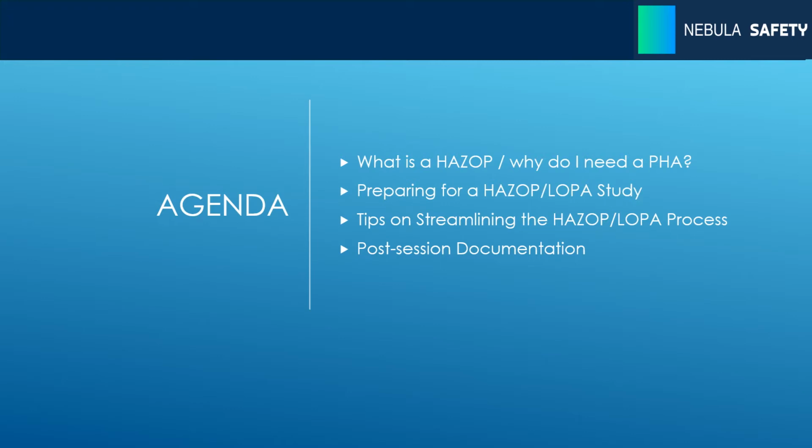These are the kind of documentation that will be requested by regulatory authorities for your normal 5-year revalidation cycle, as well as if there is ever any sort of release or accident on site. One of the first documents that are going to be reviewed is going to be the PHA documentation.